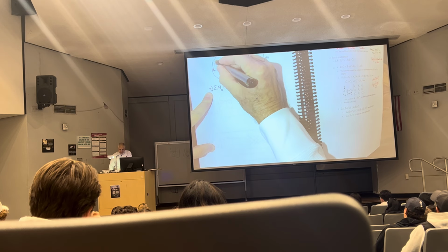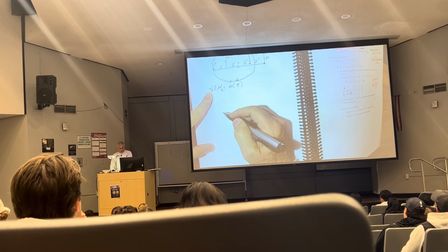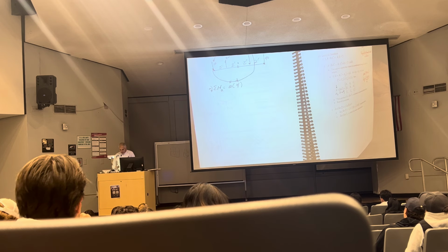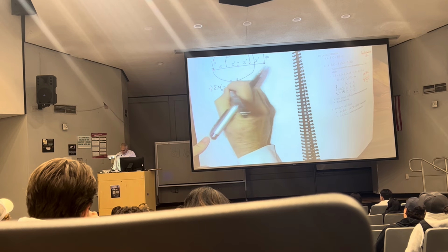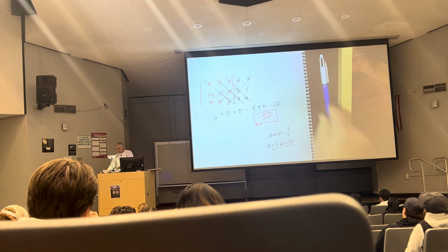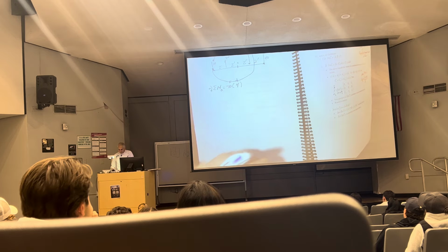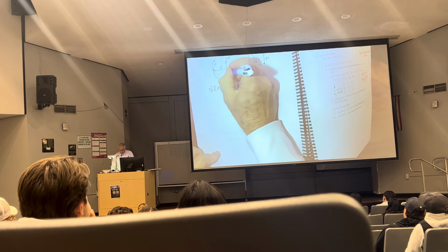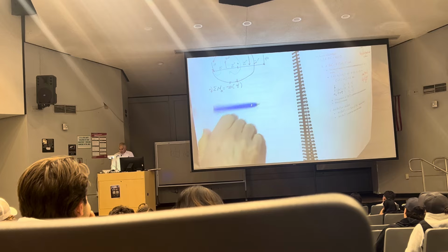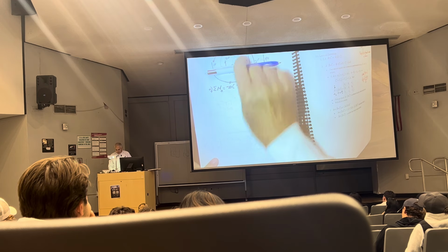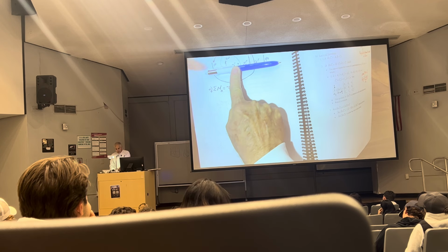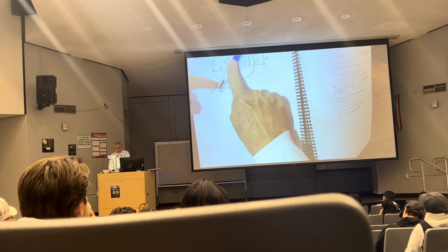What is that? Counterclockwise. Well then, I should put a negative sign on that. What is an unnatural way? This is an unnatural way around it. That makes no sense. If you want to think of it differently, let's say that's the beam and there's O, where my index finger is. I push down this way. Which way is this turning?